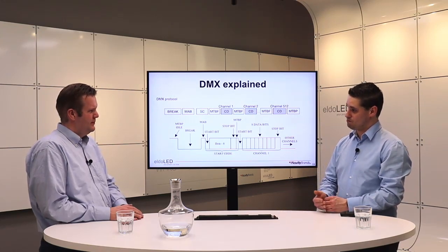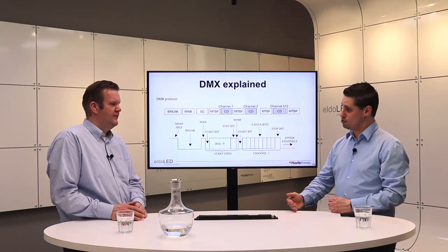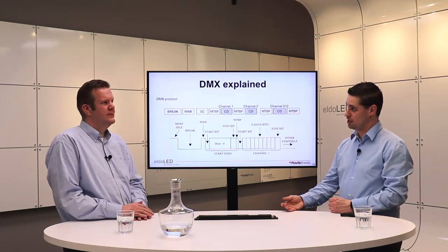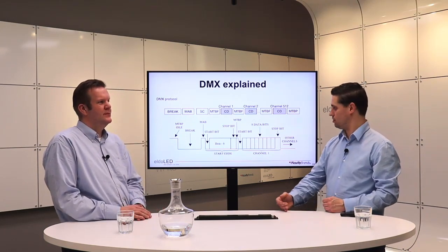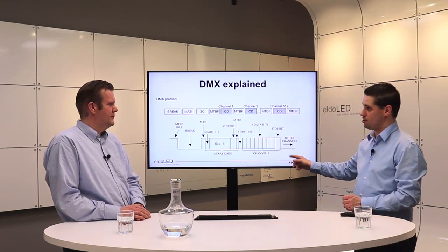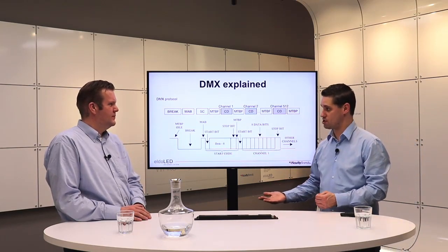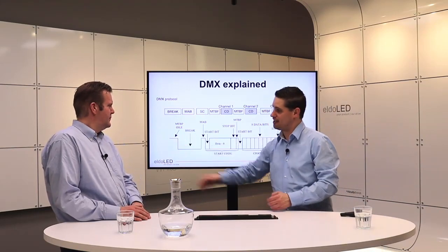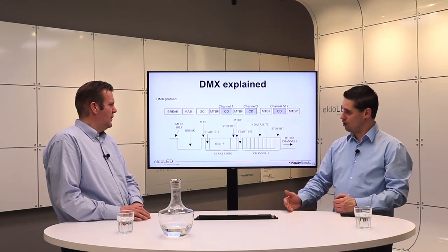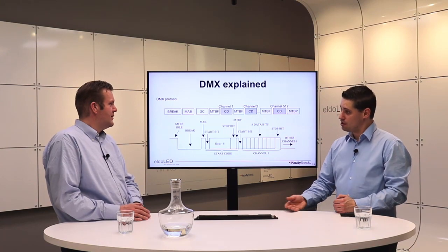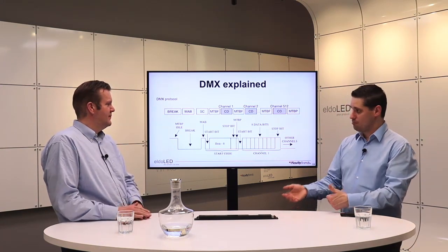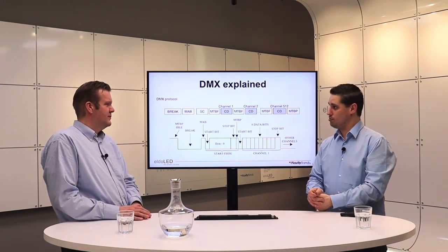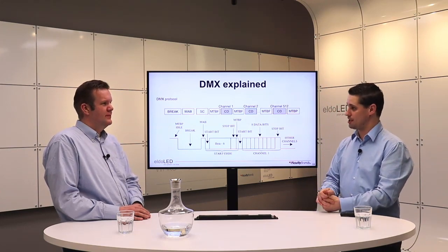In that moment in time, you could make use of the functionality that you ask a luminaire in the data train a certain command or a certain question, and that particular luminaire is answering in that idle frame of the DMX time. Okay, so that's a two-way communication then. Indeed. It can be used to address a luminaire, to set the DMX address.